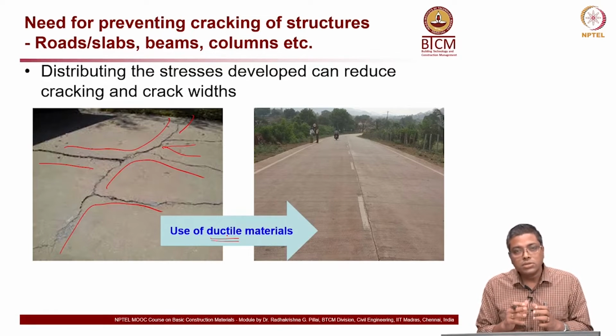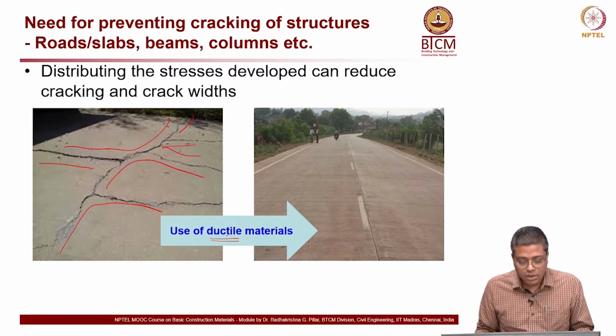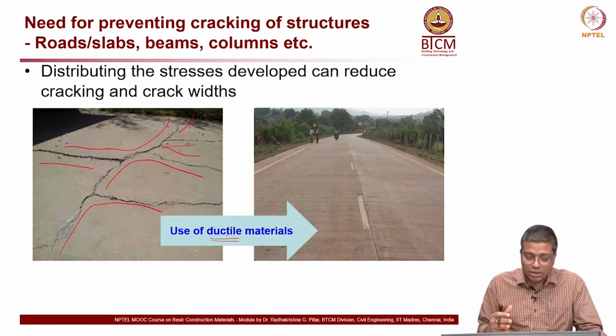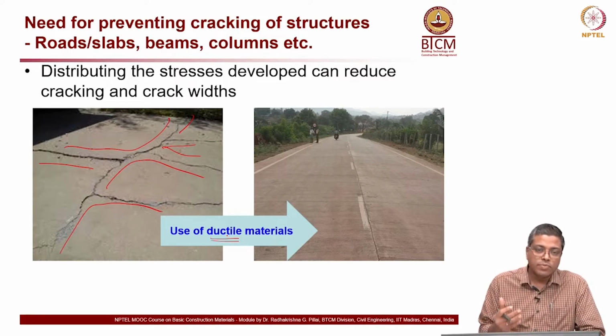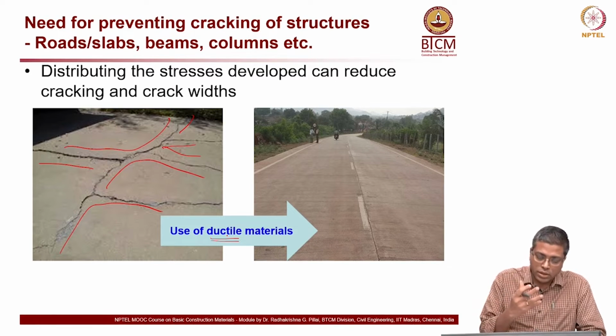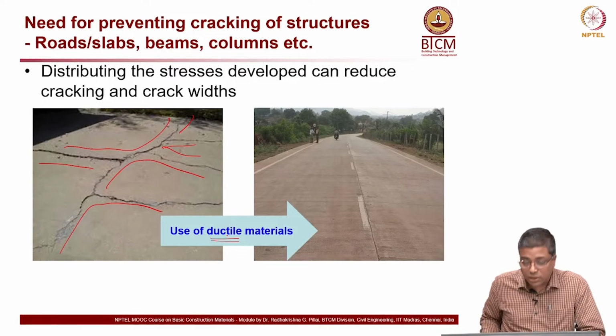That is mainly because the stresses which are developed get distributed because of the presence of either the steel reinforcement or the fibers, etc. The more ductile the material is, the more you can control the crack width, and crack resistance will be relatively better.